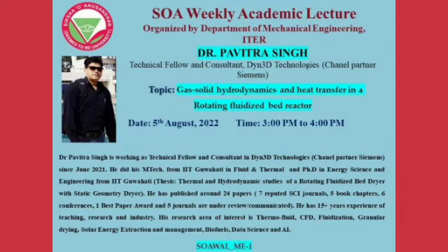So we can say this is equal to (Mi minus Mf) upon Mi into 100, and in the second case it is (Mi minus Mf) upon Mf into 100. Mi is the initial moisture content in the grain, and Mf is the final moisture content in the grain. So we can use these two formulas either on wet basis or on dry basis.